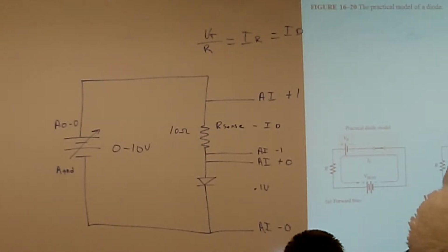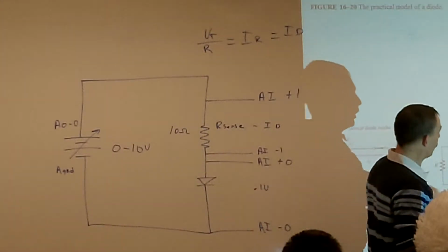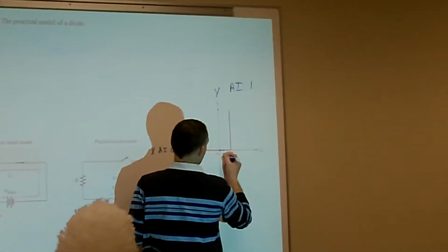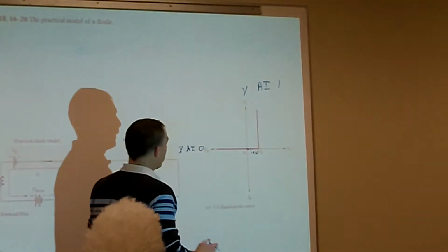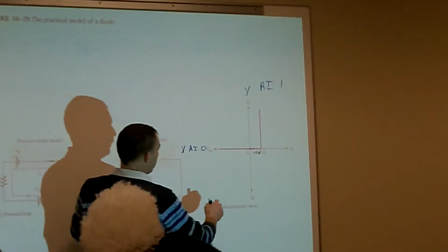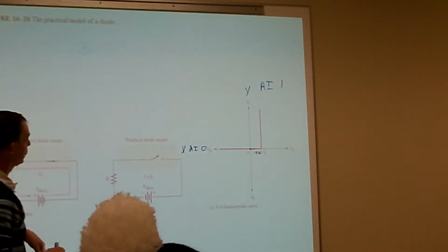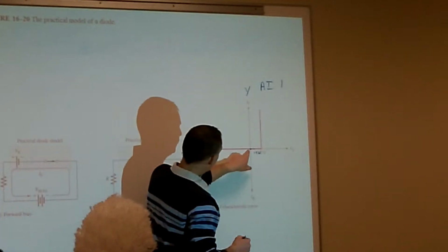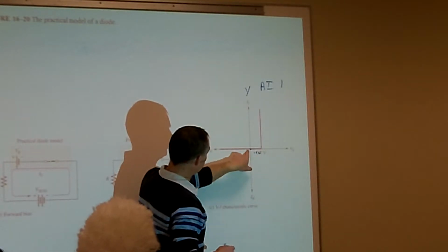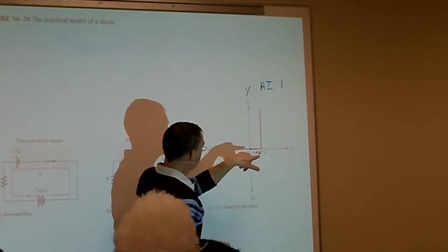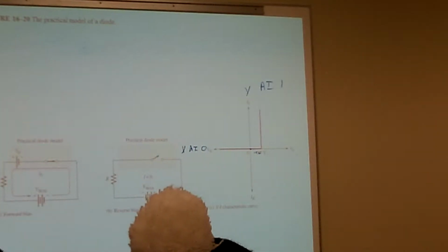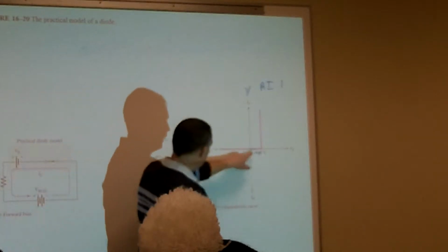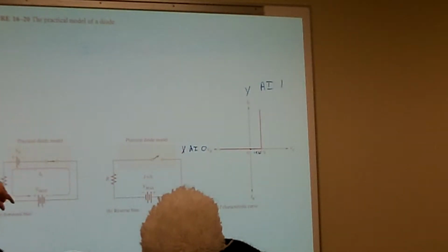So you can see on our diode characteristics curve, here's 0.7, so we're at 0.1. It's this little spot right here, at our 0.1 volts. What is it showing that we have for current at our 0.1 volts? Remember, here's 0, the center of my vector. That's 0 volts, 0 amps. So what is my current going across that sense resistor, if I have a dot right on that line right there? 0.